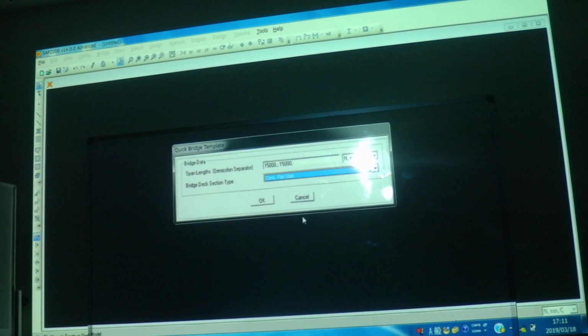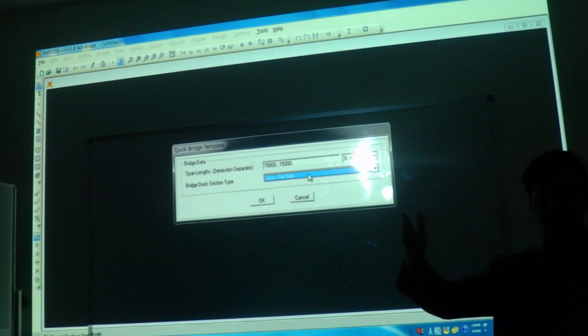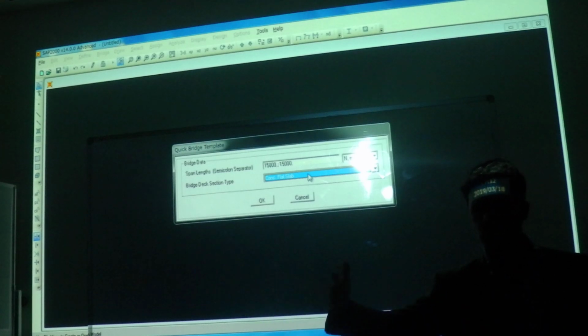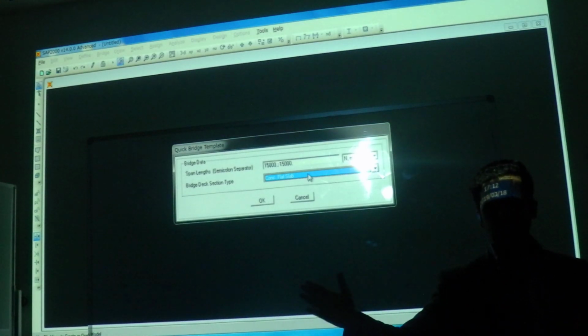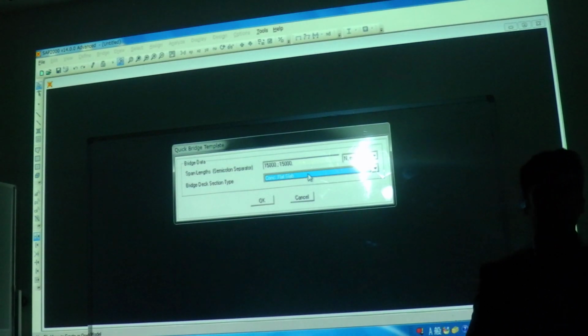But sometimes we have a continuous slab bridge. In that case, if we give it like this, it will be a 2 span continuous slab bridge. But if we define 2 spans and over the support we give a simply supported condition to the slab, I mean, we divide this bridge slab into 2 separate panels, one slab and another slab, and both slabs are simply supported, I'm just repeating my work. I'm not doing anything extra, anything new.